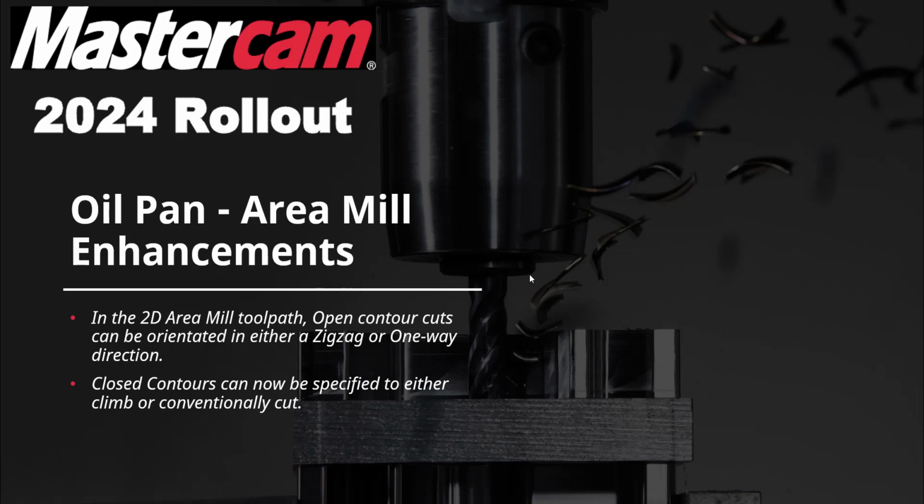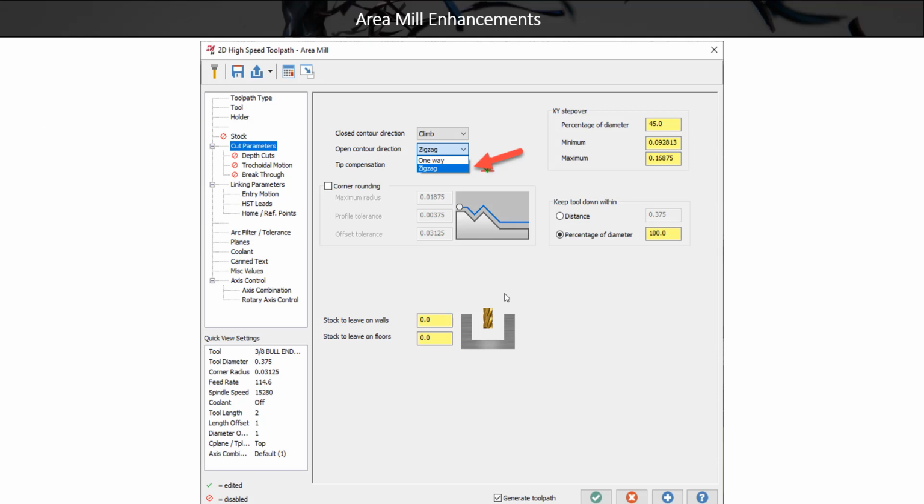Pocket is, I still like pocket for finishing floors and walls, but for finishing a floor, area mill is often my go-to. And this enhancement to 2024 makes area mill even better for finishing floors. This is not like a completely new interface. We've seen this in other toolpaths. Think like Waterline in the 3D. I can do one way or zigzag. That's what's new in area mill. Area mill only had basically one way before. It was just climb or conventional. That was it. Now I have a one way or zigzag for open contours.